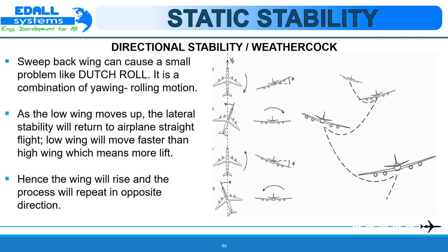Whenever the wing is disturbed from level trim, the aeroplane, left to its own devices, slips sideways in the direction of the low wing. Thus, the oscillatory rolling moment leads to some oscillatory side-slipping motion in Dutch rolling motion, although the side-slip velocity is generally small. The ratio of peak roll to peak yaw is usually less than 1 and is usually associated with the stable Dutch roll mode. However, when the ratio is greater than 1, an unstable Dutch roll mode is more likely.